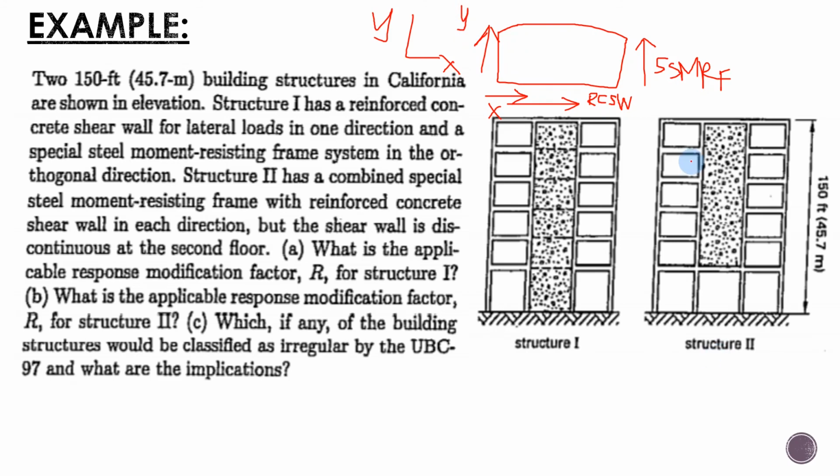So the shear wall is probably placed in the x direction because the earthquake load is larger in x compared with y. Initially, the design was probably a special steel moment resisting frame in all of the x direction. But upon checking the drift, which is caused by large seismic forces, the drift is large.